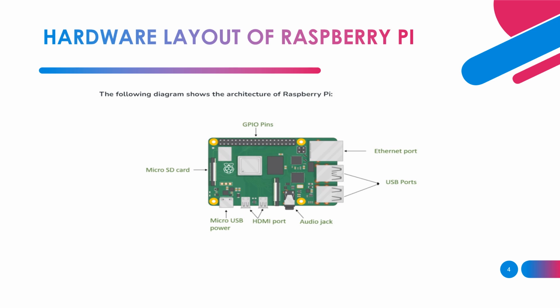This has a level 1 cache of 16 KB and a level 2 cache of 128 KB. The level 2 cache is used primarily by the GPU. The Raspberry Pi 2 uses a Broadcom BCM2836 system on chip with a 900 MHz 32-bit quad-core ARM Cortex-A7 processor with 256 KB shared L2 cache. The Raspberry Pi 3 uses a Broadcom BCM2837 system on chip with a 1.2 GHz 64-bit quad-core ARM Cortex-A53 processor with a 512 KB shared L2 cache.